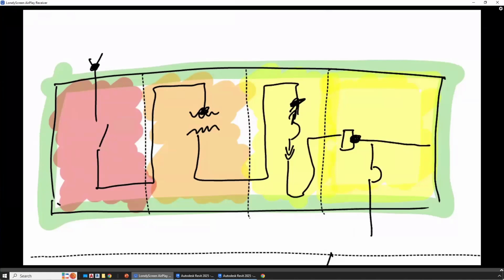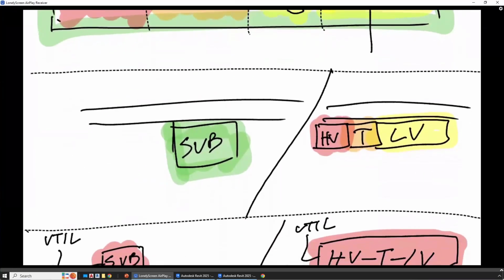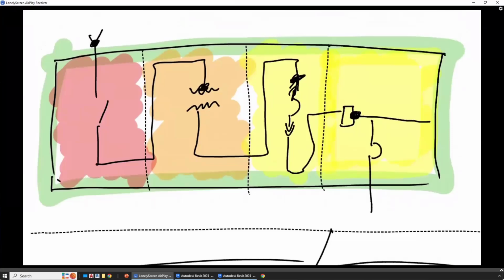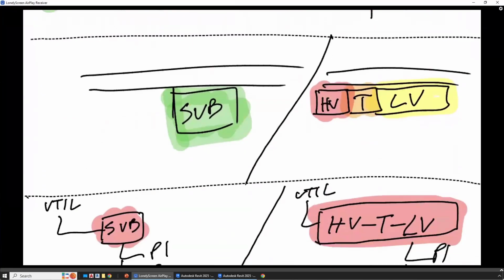When placing an ATS as the main disconnecting means on the switchboard, would you insert an actual ATS or create a new one and drop in two connectors? Again, it's a question of how you want to model that. Both ways could work. So you have to come in here and in Revit, think about what pieces you're going to insert, and then how you want that to be drafted on the single line and what you want to have happen on the calculations.